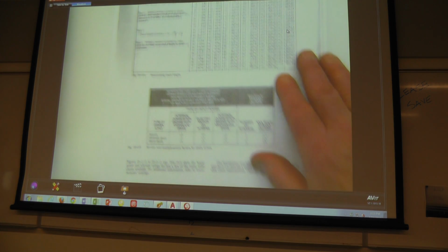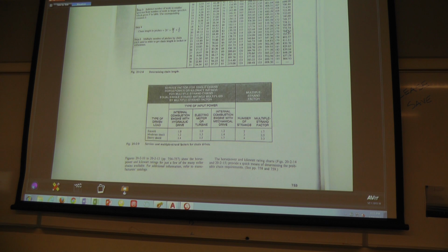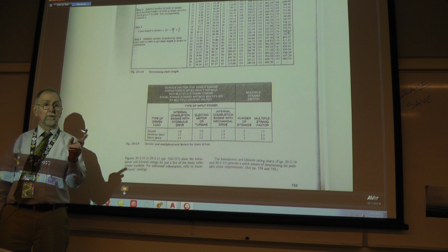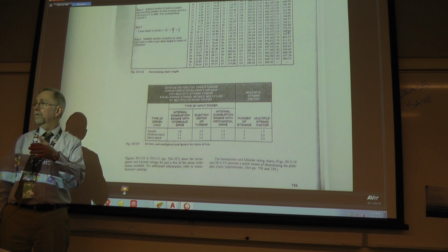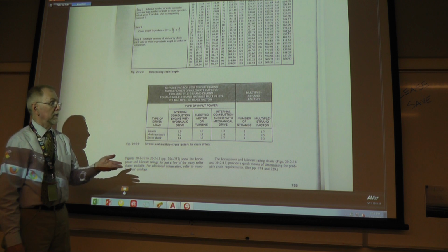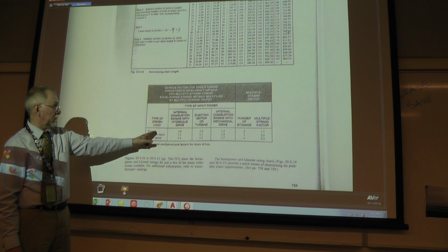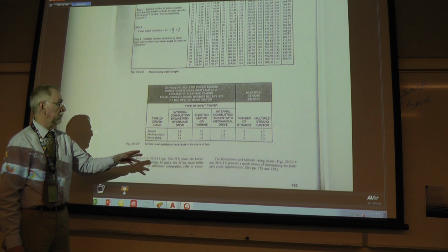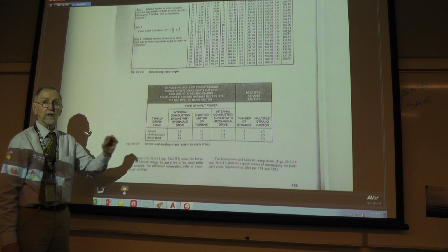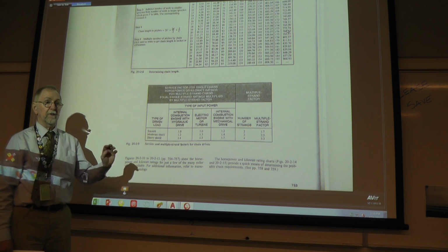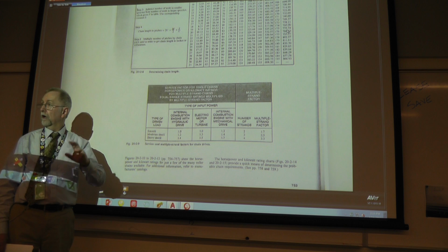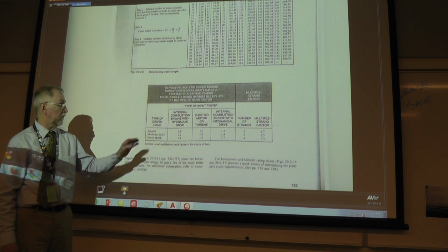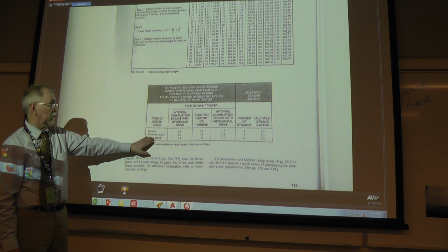Below that is another chart that, again, with V-belts, there was a chart that talked about service factors. What kind of service factor was involved with what kind of equipment was it? Here we have the type of driven load. Now with chain drives I can have a smooth drive situation. I can have one that has a moderate shock. It turns on, it turns off. I could have a heavy shock. There might be a lot of turning on and turning off. There might be vibration involved with it. So there's a certain type of load that's determined.